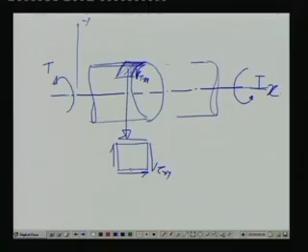Now, as we can see that we have made a bending moment in this way, means we have been bending in this fashion, M is coming. So, the upper surface will be in compression, the lower bottom side will be in tension.